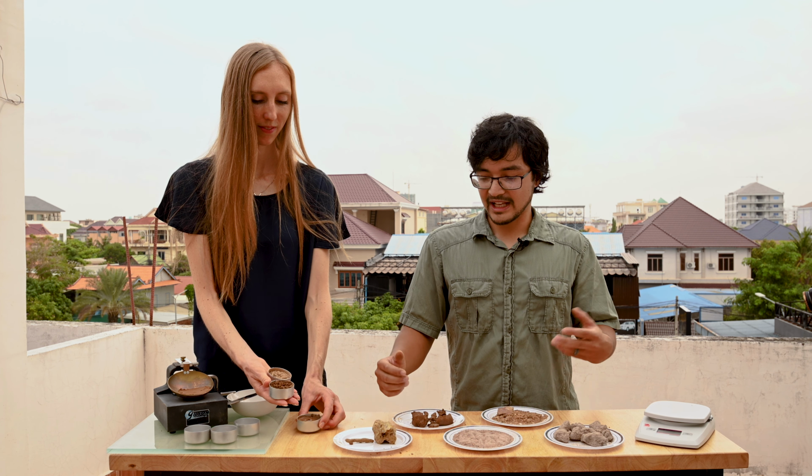So soil texture is a description of the soil particle size and gradation for coarse-grained soils and the behavior for fine-grained soils. To determine a precise gradation for our coarse-grained soils, we use a set of sieves to separate between the gravels and the sands on a number 4 sieve, and between the sand and fine-grained materials on the number 200 sieve.